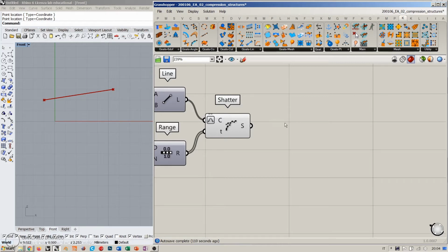Okay, so in this case, what we need to do is convert these segments into springs. Now, there are no springs actually in Kangaroo 2, which is the main difference between Kangaroo 2 and Kangaroo 1. You won't find springs here, but you will find goals. And goals are divided into categories that correspond either to geometry or to specific boundary conditions and forces and so on. So in this case, these are lines, and we are going to goals line.